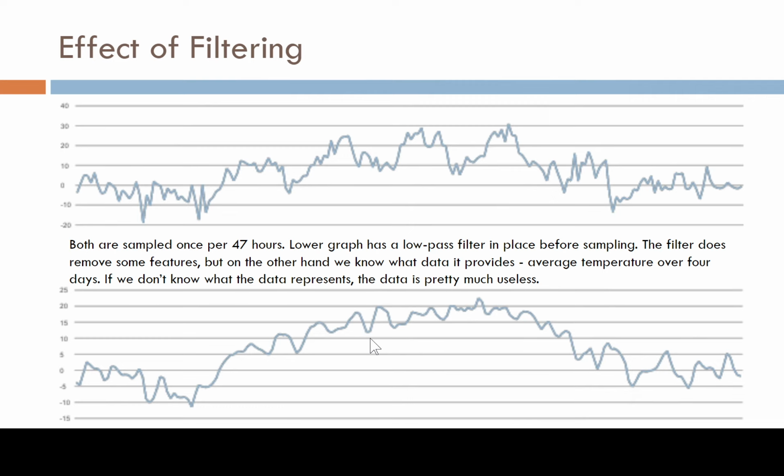This lower picture shows that when you do this sampling correctly, meaning that before the sampling you get rid of the high frequency noise in the data, then you are safe. Then your data is meaning something.